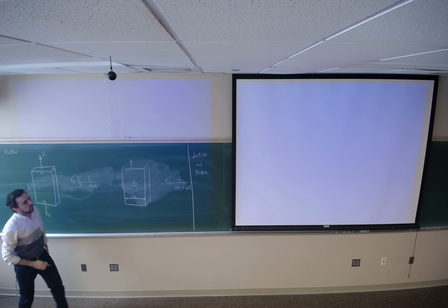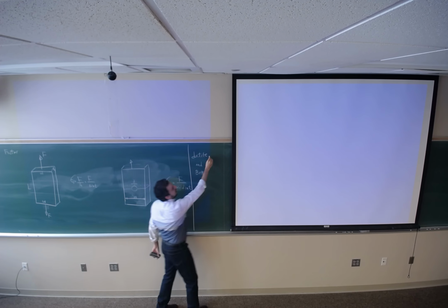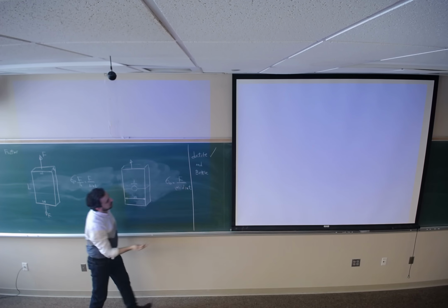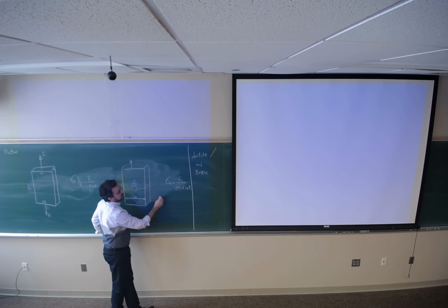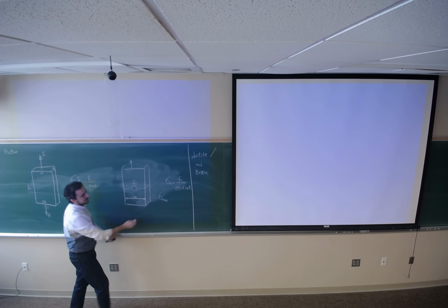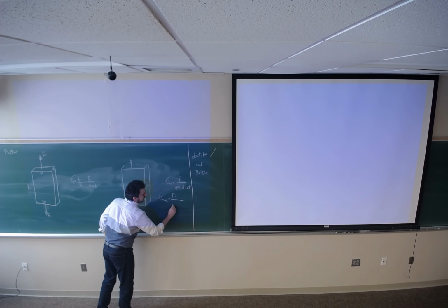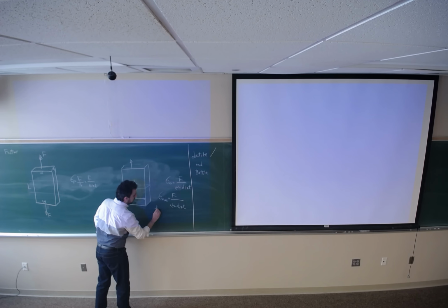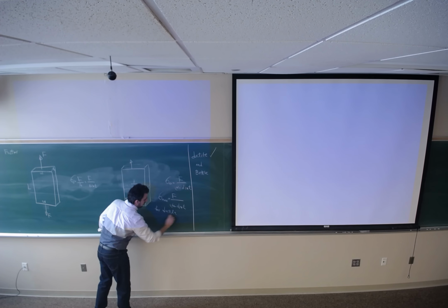So if this bar is made of ductile material, if someone asks you what would be the maximum stress applied to this bar, we can say it's going to be force divided by W minus D times T for ductile material.